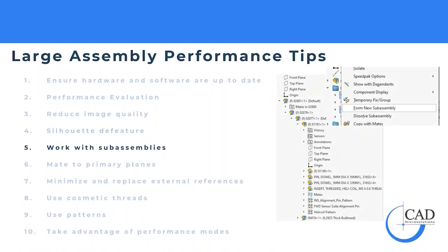Another big thing you can do is working with sub-assemblies. As you can see in the screenshot on the right-hand side here, this is from this year's assembly from Square Robot. We have a ton of sub-assembly depth. By that, we go sub-assembly into a sub-assembly into a sub-assembly. I highly recommend doing that. Every time you can break something down into a sub-assembly, it means it's easier to work on just those components because you don't have to work in a large assembly for every sub-assembly.